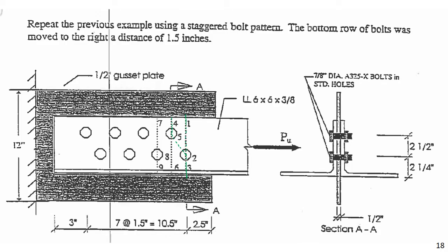So let's see, what other failure modes do we have? Well, we could have bolt strength, but we're not going to be worried about that one right now, because that's more later in the semester when we look purely at connections. And in this particular one, block shear is actually going to be the same. Block shear is not going to vary substantially, because here we calculated block shear based off of a failure line kind of like this before.